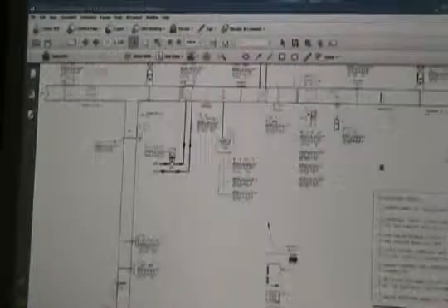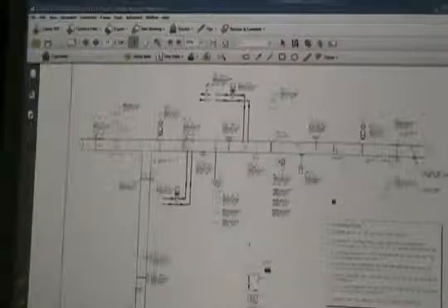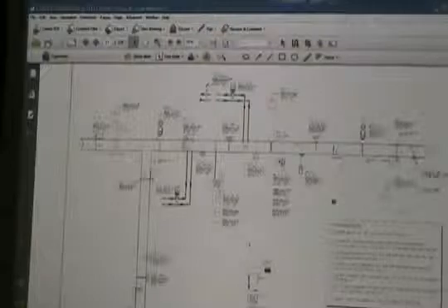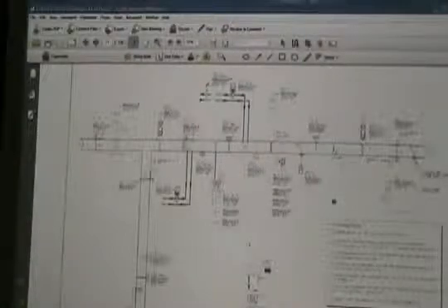So that's a typical air handling unit. Next week we're going to add an economizer section back here and exhaust fans. But the intent right here is to take every one of these devices. We talked about the outside air damper and its electric actuator, the airflow measuring station, the filter differential pressure, return air dampers, and the return air temperature sensor. Obviously, what we're doing is monitoring that temperature. We're not really doing anything with it. Humidity sensors controlling the humidifier.